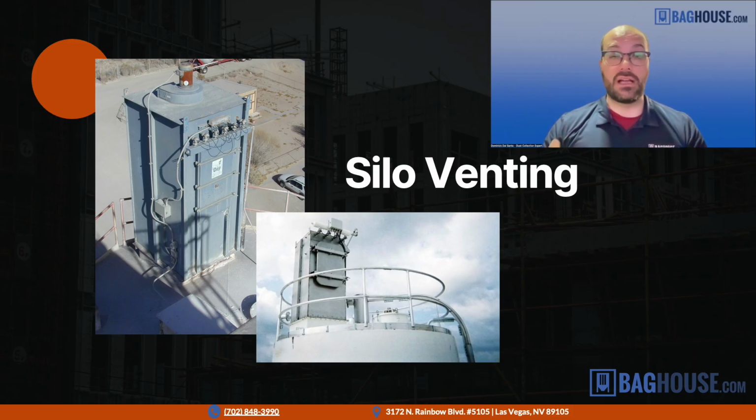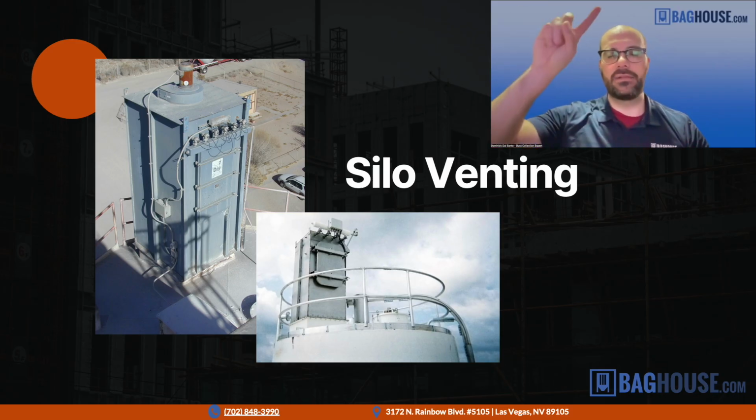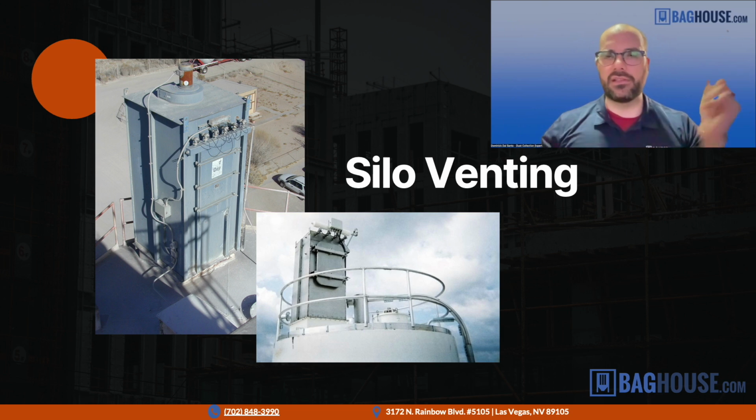So most common setup, a big silo, where when the trucks or trains come and they blow the material in, or you have a big screw conveyor that drops material into a silo, on the top of the silo you have a bin vent dust collector. As the air is displaced, it goes through the filters and out the dust collector just like normal.